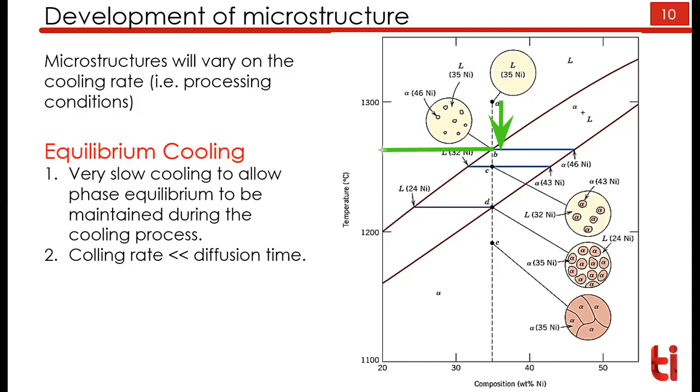When you touch that boundary, I assume solidification just starts, so clusters just grow or nucleate from the material. In the diagram you can see these irregular shapes shown here. They are basically alpha particles nucleated in the liquid. I'm not drawing that one because it is already there in this picture.